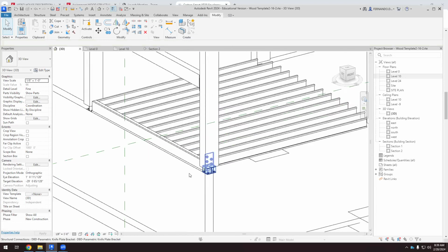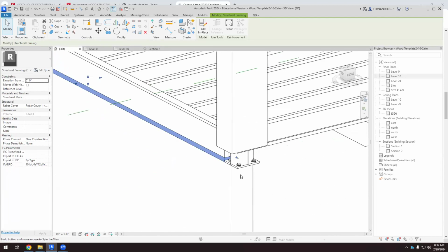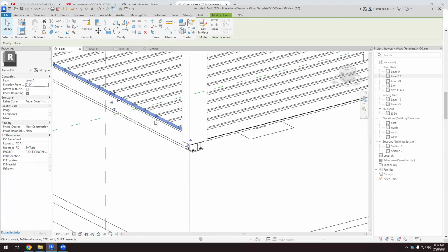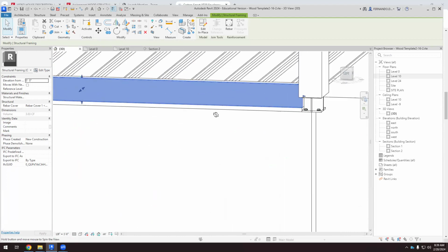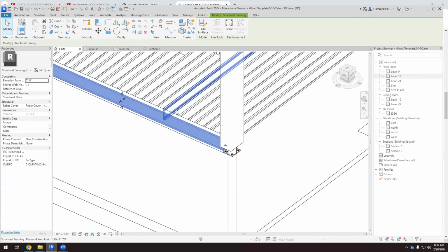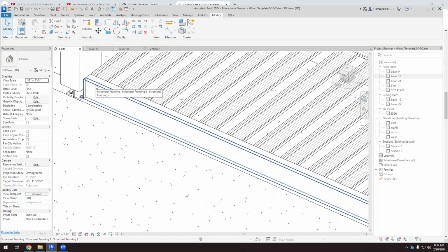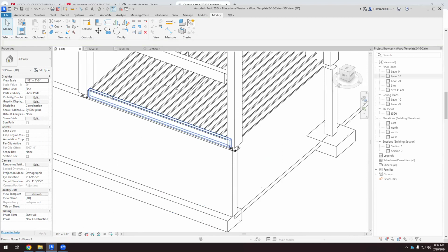The joists are resting on this first wooden element that I placed here. And now I need to cover the joist, and I did it with thermal insulation to prevent the thermal breach. And then I cannot expose thermal insulation to the outdoors. So I need to create that wooden element. That's the exterior finish of this.